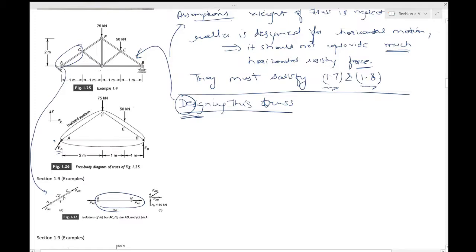I think this is D, not exactly marked, but this is D. Now, in figure 1.27a and b, free body diagrams are shown, of course, where the weights of the bar and the frictional moments around the pin joints are neglected. Okay, frictional moments about the pin joints are neglected, the weight is neglected, and hence this free body diagram should be good enough. Two force member, as you know already.